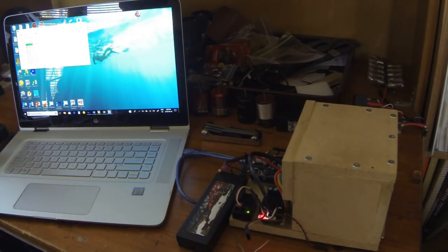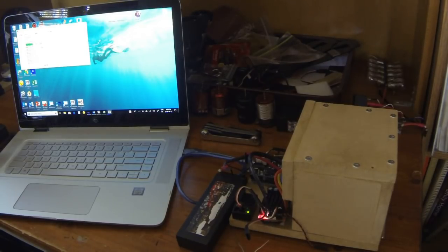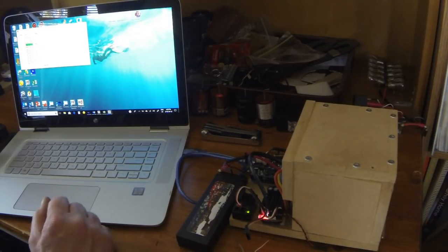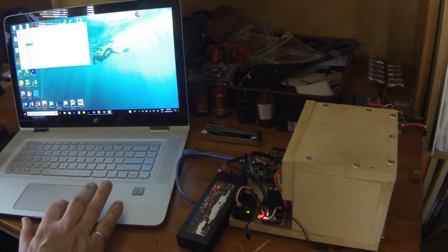Okay, so that's the end of a test. You'll notice that the test went significantly faster than the Mini Pro, and the reason for that is the inertia of the flywheel system is quite a bit lower than the Mini Pro's. It's less than half the inertia that the Mini Pro has. Okay, let's do some comparison. We'll go into RC Crew Chief and compare the dyno results.